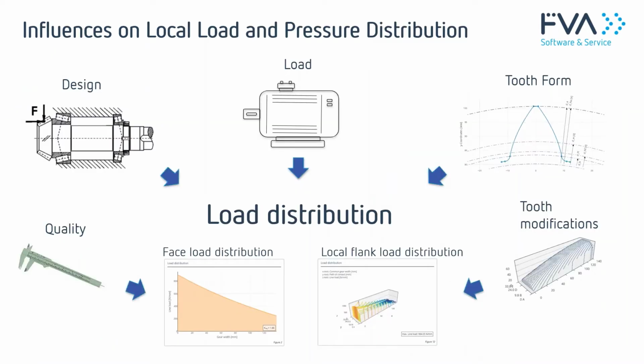But starting with the main focus for today, the local load distribution, I want to first recapitulate what the basic influences on the local load distribution are. When we are talking about the local load distribution, that's the picture here at the bottom of the slide. We are looking for the different pressure values, sliding velocities or temperatures at every point of the tooth length.